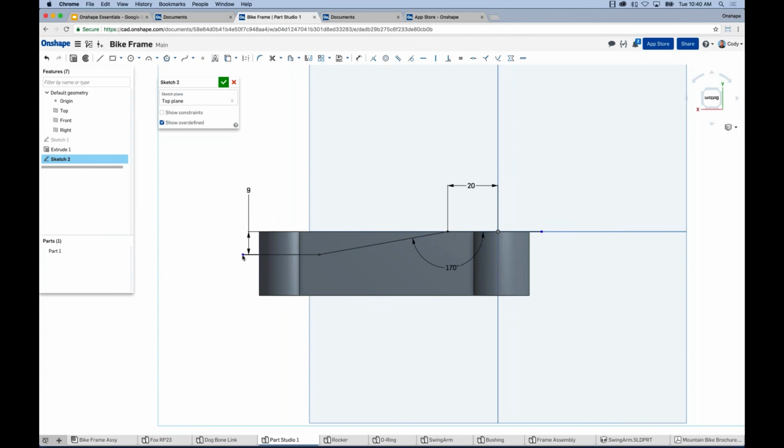All right, so a question that's popped up: can dimensions be entered as an equation? The answer is yes, but there's one caveat. You have to use what are called variables in Onshape. So first step, create the variable, then you can input the variable into your dimension. And you can say this minus this divided by this plus this if you want to build out those equations. But they require you to create variables first. So if you're going to do any more digging on that, I would definitely check out, just do a search for variables in Onshape.